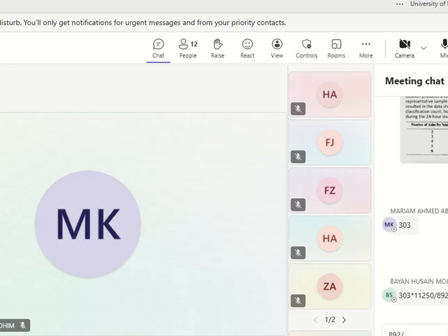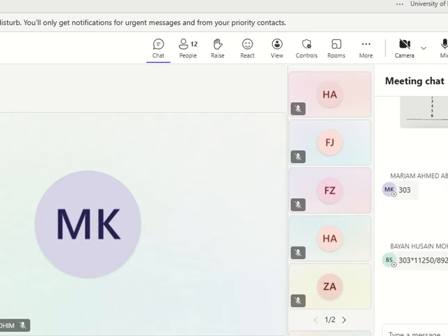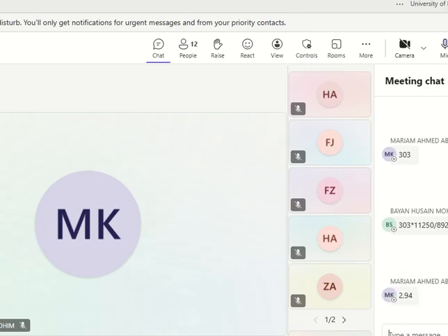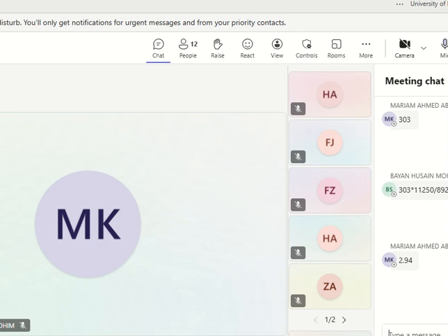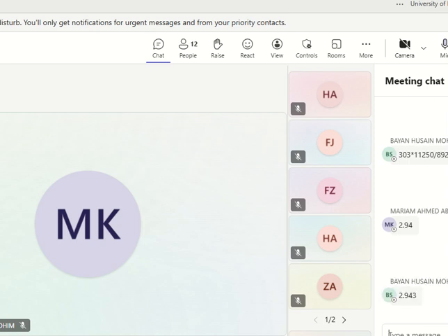892 divided by 303. So how much is this? This is my conversion factor. So I got 892 axles and 303 vehicles. What is the conversion factor here? 2.94. So every vehicle has 2.94 axles on average.